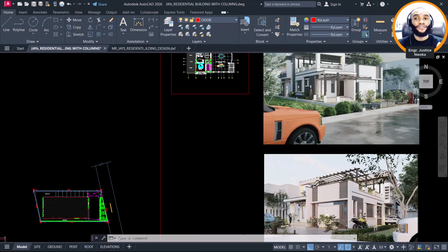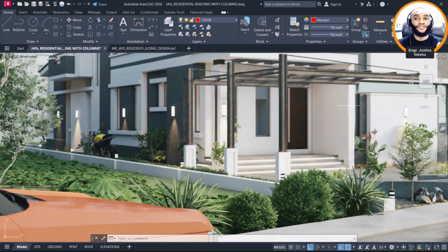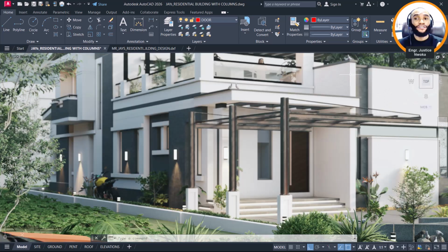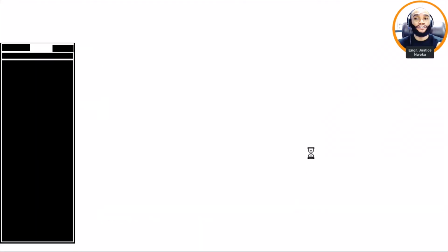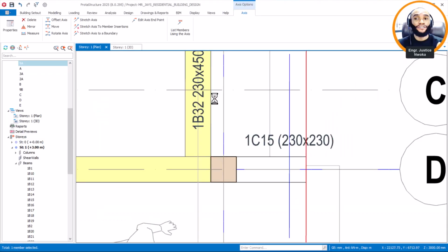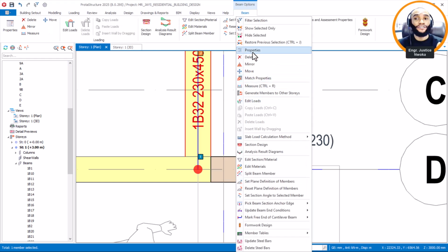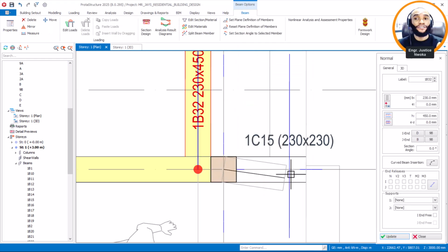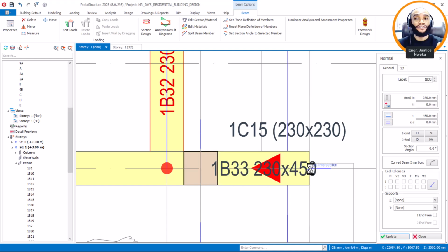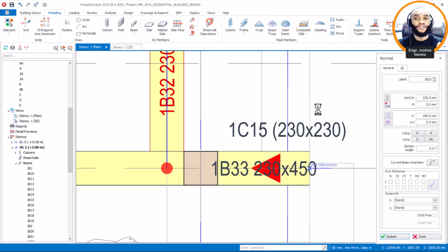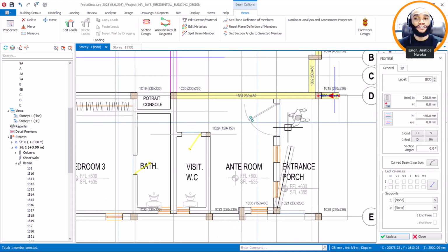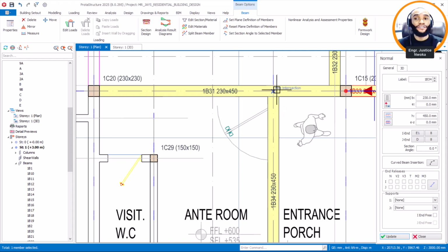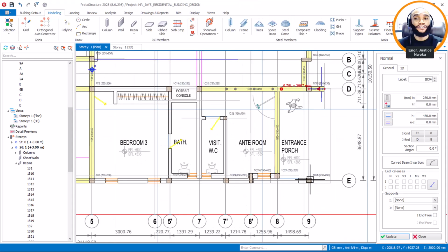You can see this wall here. There is also a wall around at the top here, so there is a little cantilever beam that's going to carry that wall. With that, we want to achieve that. So I'll click on this beam, right click here, and open the properties of that beam, and then continue again from here all the way to flush it directly at this face. That's fine. So we now have a cantilever beam there. Again, I'll continue, escape, then flow from here all the way down here. That's fine. This column you're seeing here is a stand-alone column.